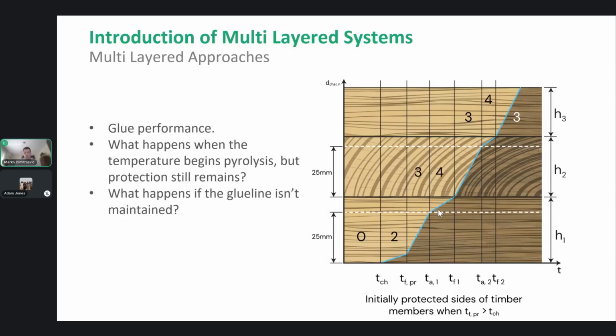The new Eurocode introduced much stricter validation and testing to ensure the glue line maintains structural integrity under fire. You can check out more details about this in Annex B of the new draft version. On the other hand, in the Austrian National Annex, there is a classification of MUF adhesives, where there is no delamination, and PUR adhesives, where delamination will occur. In that case, the charring rate will speed up again significantly.